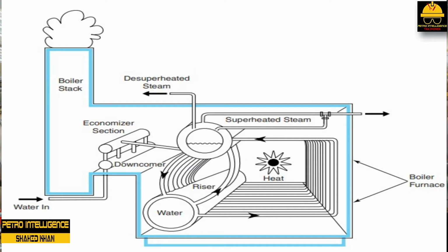Cooler water flows from the upper or steam drum through the downcomers to the mud drum, the lower drum, and then rises as some steam is generated. Circulation continues, and makeup water is added to the upper drum to replace the steam that is generated. Water circulation continues in a water tube boiler because steam bubbles in the lower drum move up the riser tubes and cause water density to decrease. The cooler water in the downcomer flows into the mud drum.